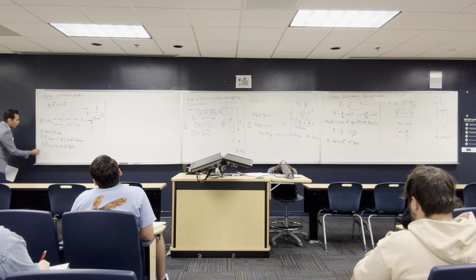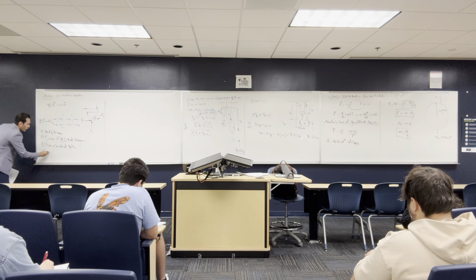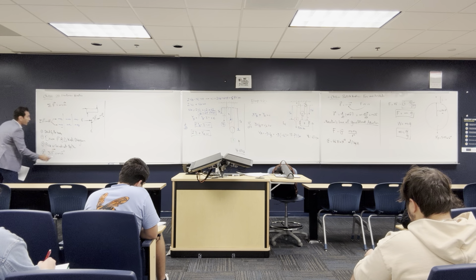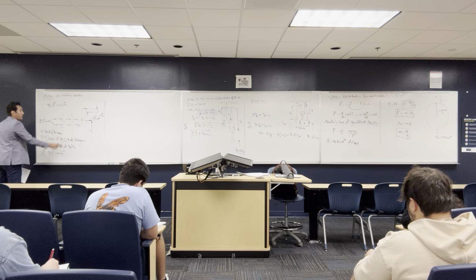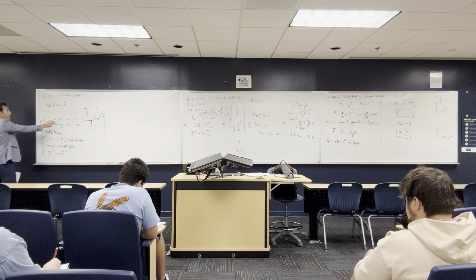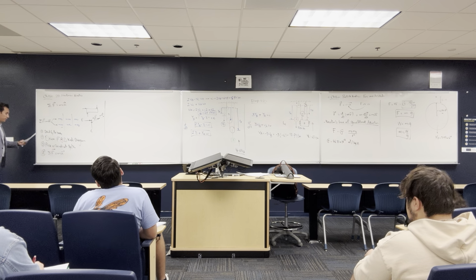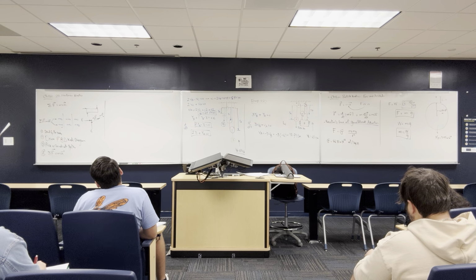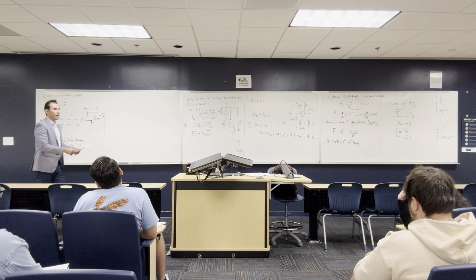Either X and Y, tangent normal, or R and theta, because in the problem I'm not going to tell you what coordinate system you should pick. Number 4 is to apply Newton's second law, the summation of the force equal to the mass multiplied by the acceleration, where you can pick x and y, tangent, normal, or r and theta. And then solve using common sense. Okay, those are the steps. But let's see how we do this in real problems.